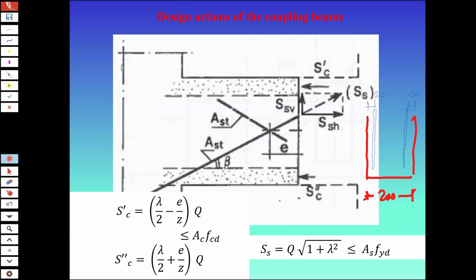I will not go lower, because nowadays, in most of the cases, 8 millimeter diameter is the lowest diameter in which you find steel with ductility requirements which are fit for seismic design. 6 millimeter bars are in what we call A grade steel, which is not ductile as C grade.